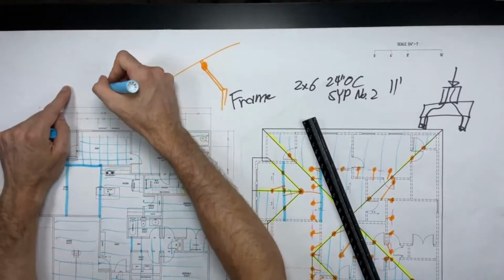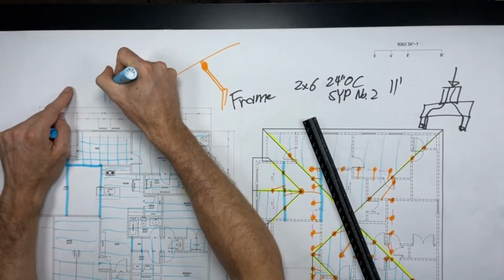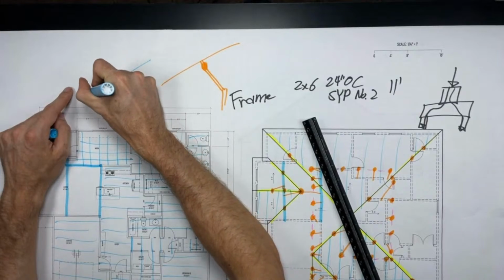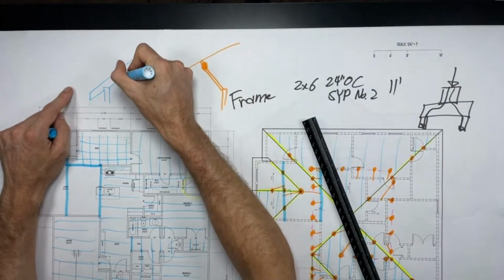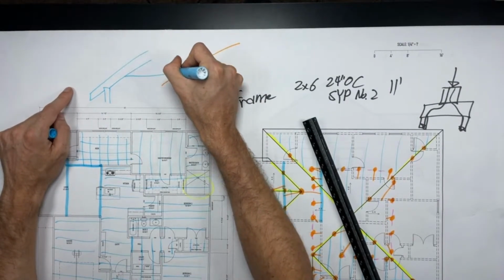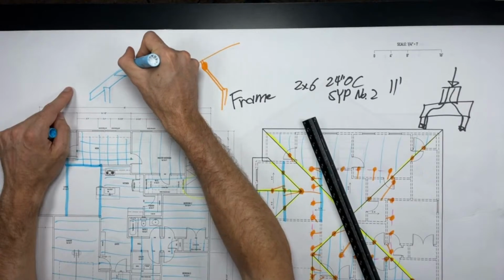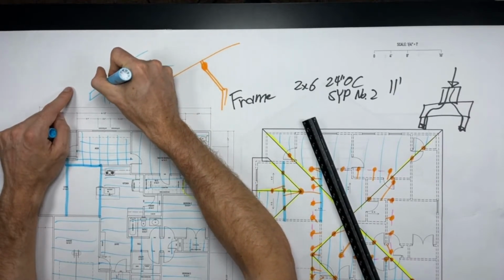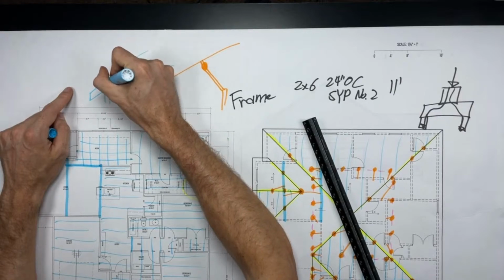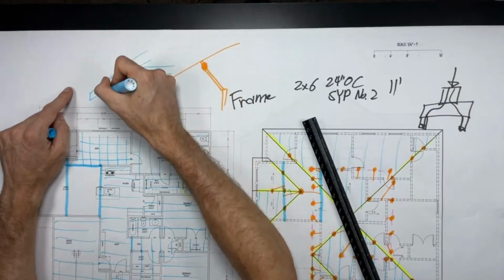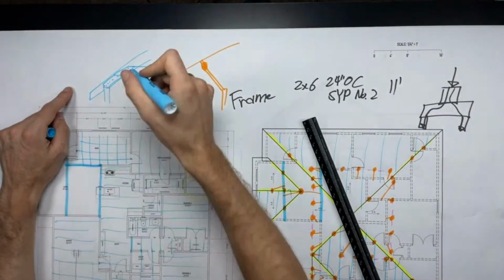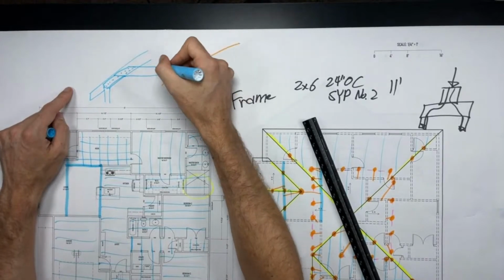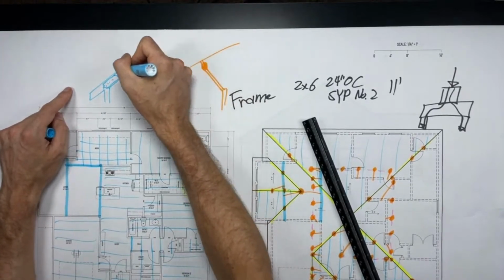So if I'm drawing this on the wall, here's my wall. My rafter goes up, and it does that. My ceiling is here, and my 10-foot starts here. So that means my ceiling joists are going to come in here like this, get nailed to my rafters. And they're going to put a block in here like this and nail it to the bottom of the rafters, so there's solid wood supporting it. And that is how they're going to hold the ceiling. Therefore, I want my ceiling joist to be in line with this.